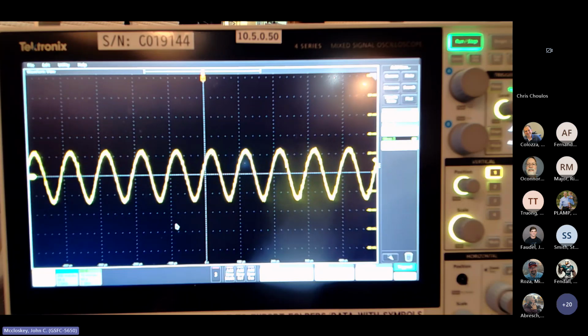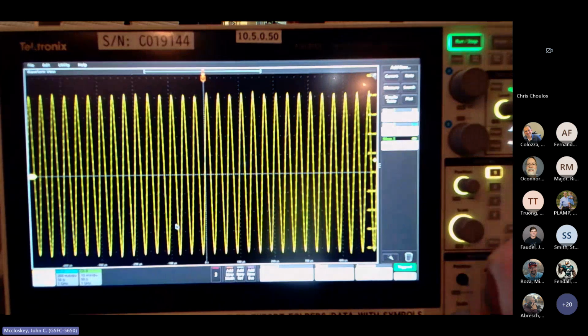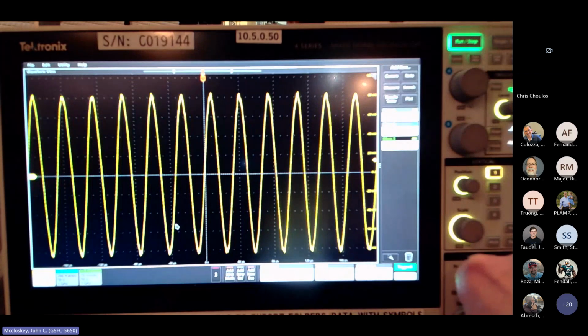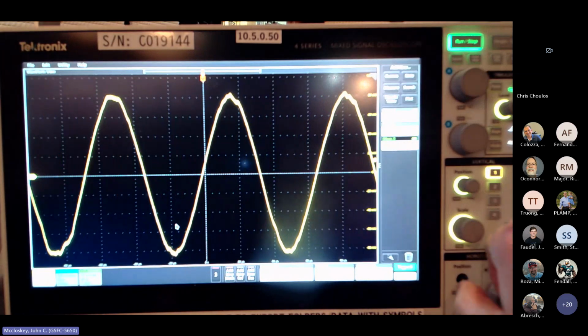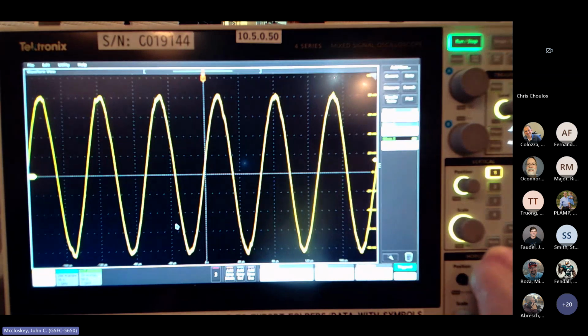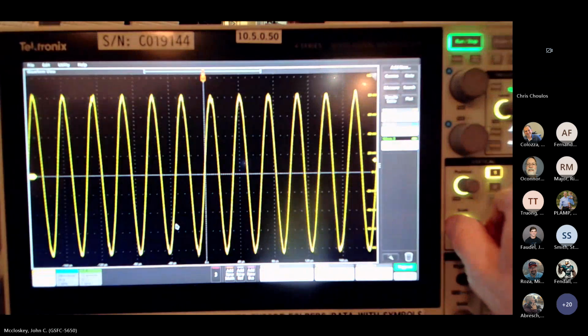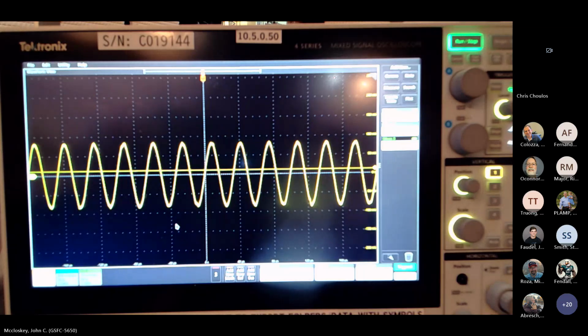All right, so now going to 30 kilohertz. I'm just doing a simplistic sweep here. When you do this for real, you'd have a lot more values in between. But I'm going to go to 30 kilohertz. Basically, on a log scale, that's roughly midway to the next decade. So 30 kilohertz. All right, our signal level goes up as we expect it would, because we're on that slope part of the insertion loss curve. All right, so now we're looking at about 57.5 millivolts RMS.